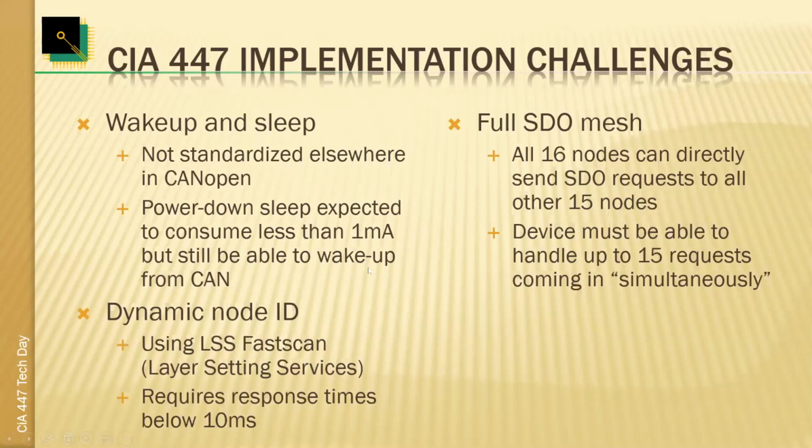And the wake up cycle can be quite long. If something changed in the network or is behaving oddly, then the gateway really has to ping each and every device and see if it's still there and comes up. This can go really in a few hundred milliseconds if nothing changed in the system. But if there's a single node that boots up too slow, because maybe there's a Linux or Windows PC behind it, or something which is not permanently connected, then the power up cycle can easily extend to several seconds. And that is not really acceptable in all applications.